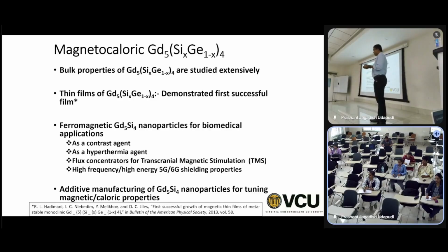It's a reversible process. So if you take down the magnetic field, it cools down, right? So if that is the case, we can use it for refrigeration or air conditioning and so on and so forth. Because it's more efficient, and instead of a compressor, you use a magnetic field, turning the magnetic field on and off. So you can get the heating effect more efficiently.